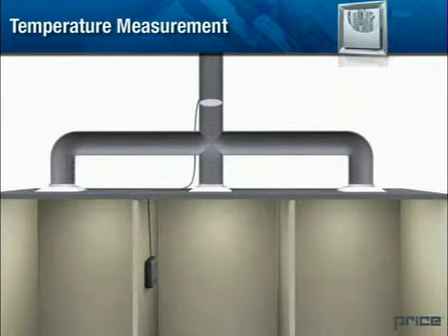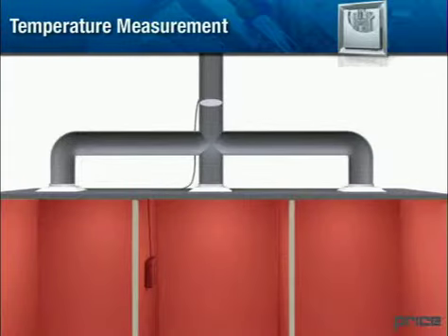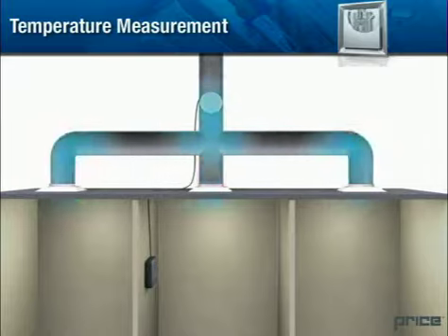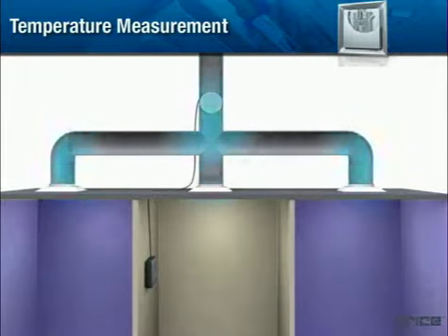Single duct VAV terminal unit. Here, a single duct VAV terminal unit is used to regulate the amount of air supplied into each room. Since there's only one VAV terminal unit, there is only one thermostat. The thermostat signal will determine how much air is supplied during cooling. When the room is warm, more air will be supplied to the diffusers, but a problem arises when the other two rooms without the thermostat don't require cooling.